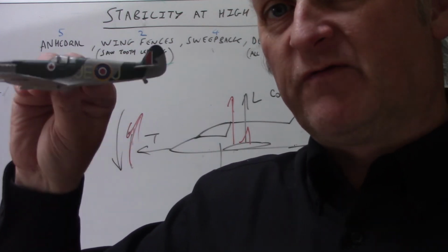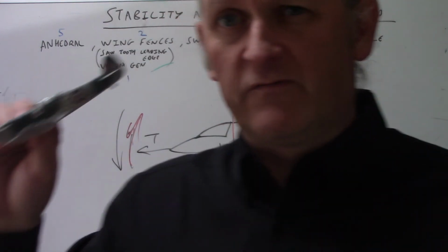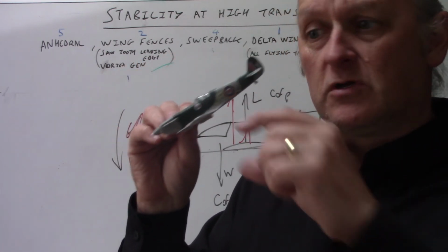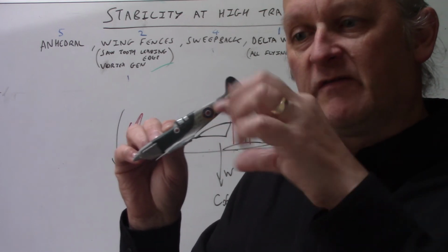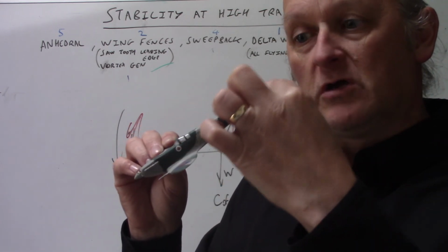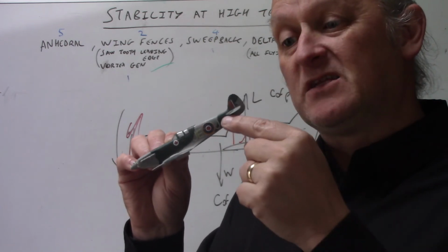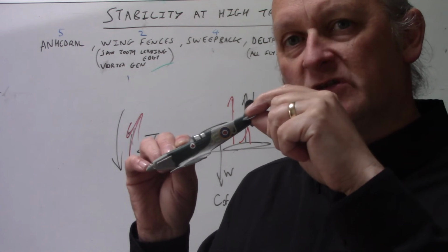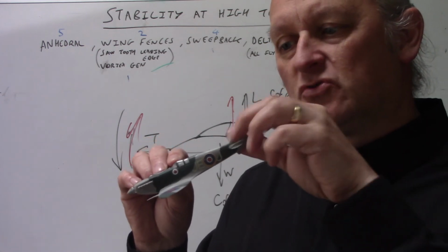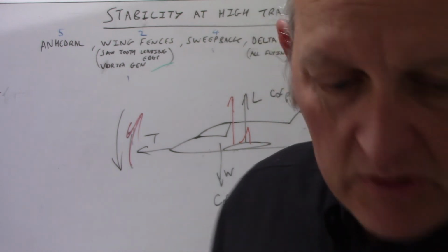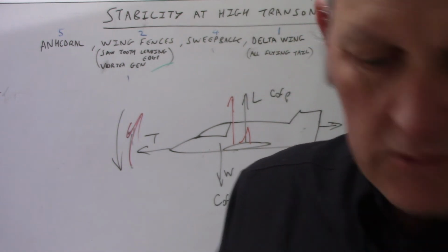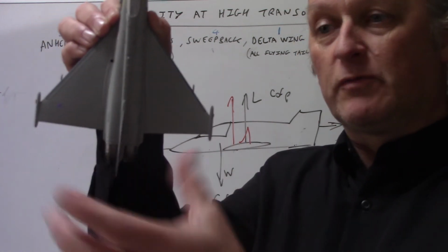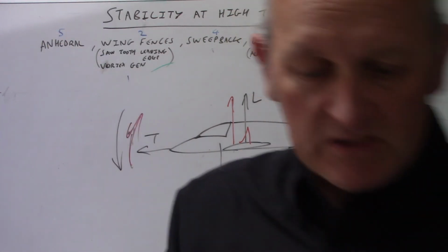What they found with Spitfires diving to try and intercept V1 flying bombs was that when the aircraft was in a dive approaching the speed of sound, the turbulent flow off the back of the wing was actually a big cone, which was affecting the tail, and the tailplane itself had separated flow. So how did they get rid of that? I'll give you a clue. If you get rid of the tail and have a delta configuration, you don't have to worry about separated flow affecting and buffeting the tail.